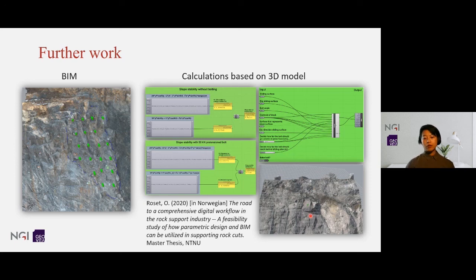And this will help engineers to easily produce designs, and ensure that the design will comply with the standards. The next procedure is to enhance the workflow and information flow between design and BIM, and make it easier for production. We are developing a procedure on how to use Rhino Grasshopper to export design to BIM, where each of the objects will carry metadata that tell you about, for example, the bolt diameter, the bolt length, and also material.